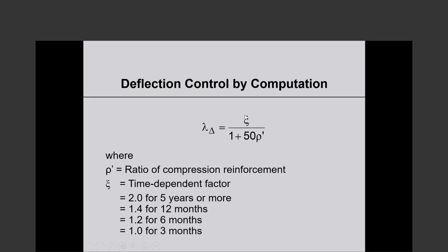And this psi is a time-dependent factor. So if we are interested in deflections 5 years or more from the time of loading, the psi is equal to 2.